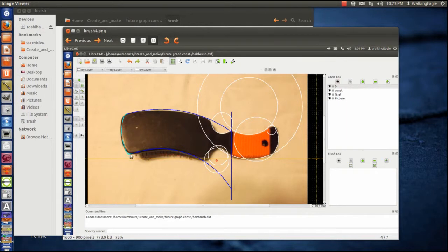What I also did was use a round function, which is built in CAD, but basically what it does is it takes about 3 steps at one time. It takes and makes a circle that's tangent to 2 points, and then it trims everything off so that you don't have the whole circle showing, and you don't have the 2 endpoints, although something went wrong right here. And then I knew that was final, so I changed the layer on it. Okay.